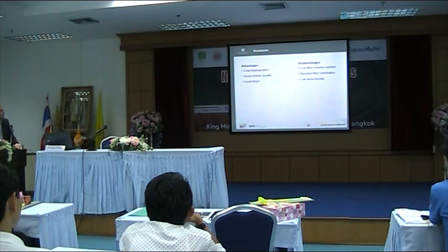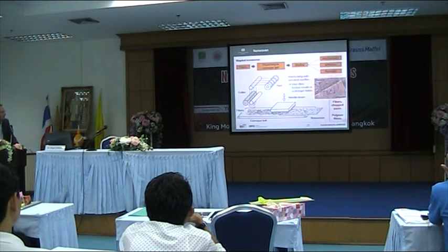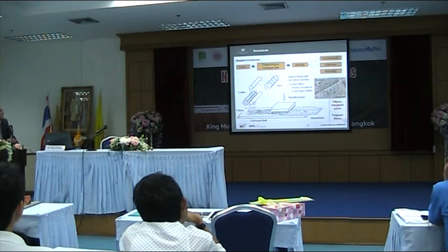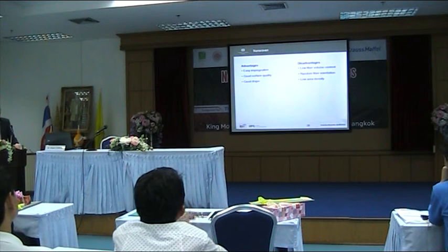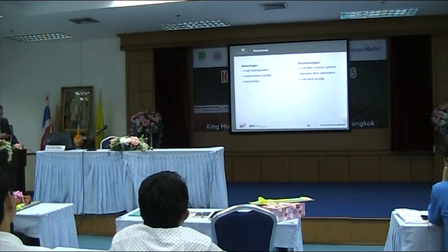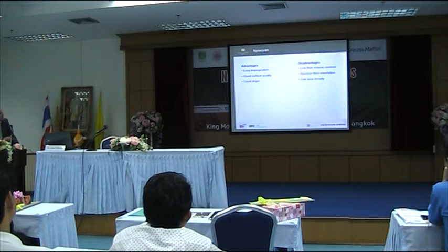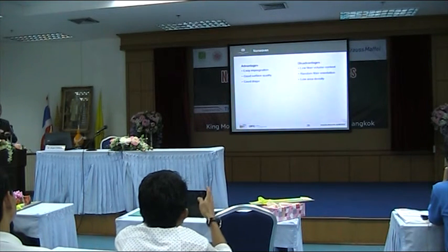So, looking at non-woven, you have, for example, chopped fibers from a yarn which is cut, or fibers coming directly from the natural fiber producer, and normally you have a mechanical binding with such needle beams. The properties of non-woven prepregs are that they have more or less easy impregnation and a good drapability because the fibers are not so long.